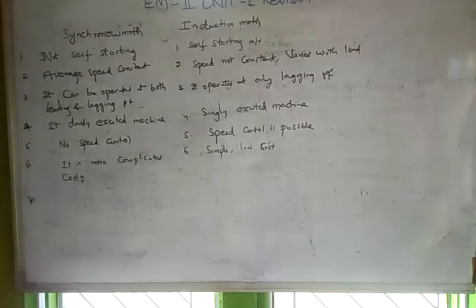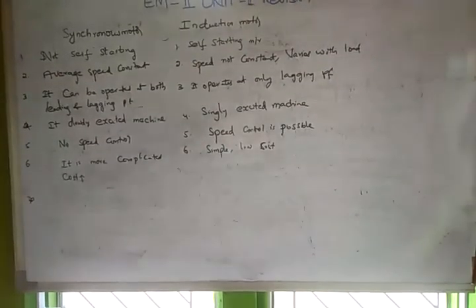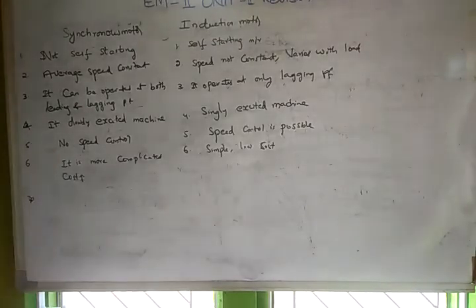So the synchronous motor is not a self-starting machine, while the induction motor is self-starting. In the synchronous motor the average speed is constant, whereas in the induction motor the speed is not constant. The synchronous motor can be operated at both leading and lagging power factor, while the induction motor operates only at lagging power factor. Speed control is not required in the synchronous motor, but in the induction motor speed control is possible, and we have different kinds of speed control methods.